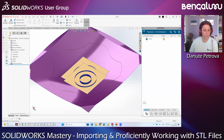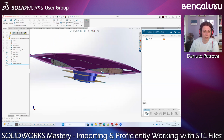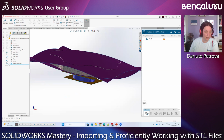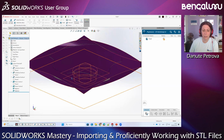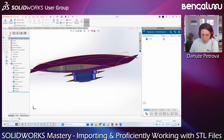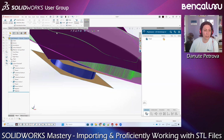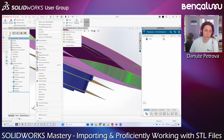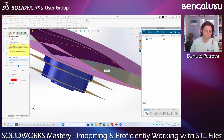Oh, it seems by mistake I exit my wizard. But that's not a big problem too. As you can see, the faces that we already converted are there, and we still have the meshes that we haven't converted, which is actually only this one. And for this one, I can start the mesh preparation, surface wizard again. It's not a problem. I will go again on the guided creation, split line if you have some.